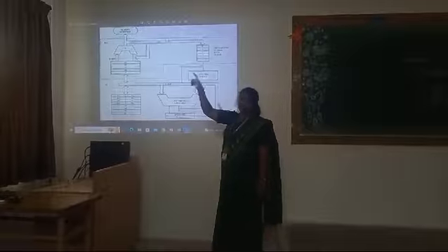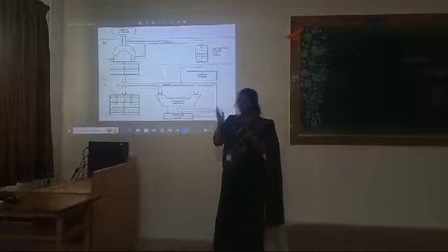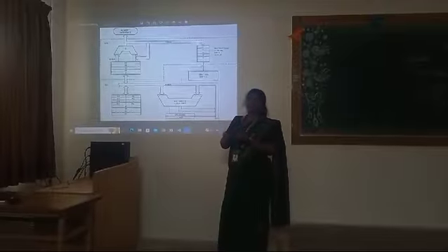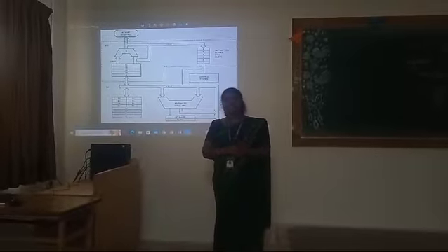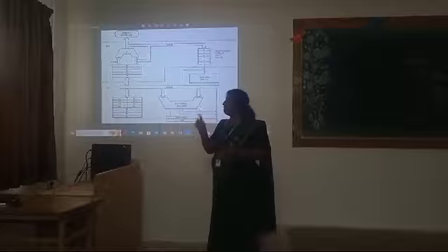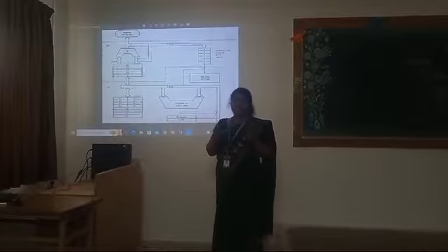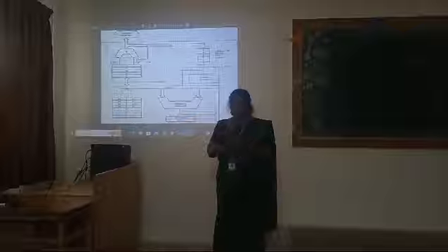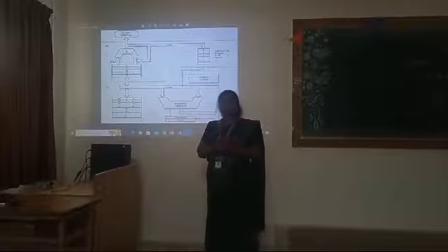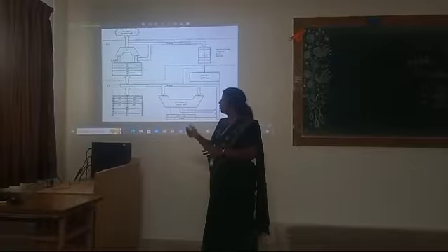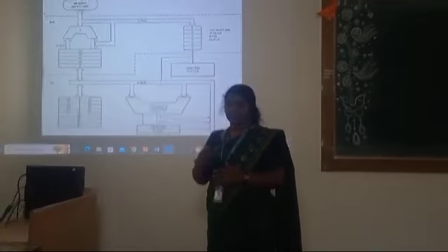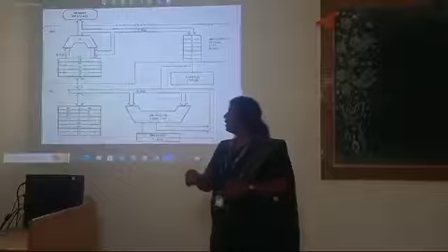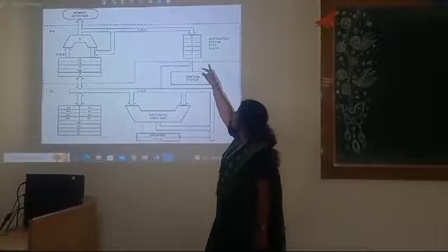The function of the summing unit is to combine, that means it will generate the 20-bit address, okay? Usually the capacity of the registers is 16 bits, but we need a 20-bit address, so that address is calculated by appending the segment registers along with the pointer or index registers. That is processed by the summing unit, okay? Fine.